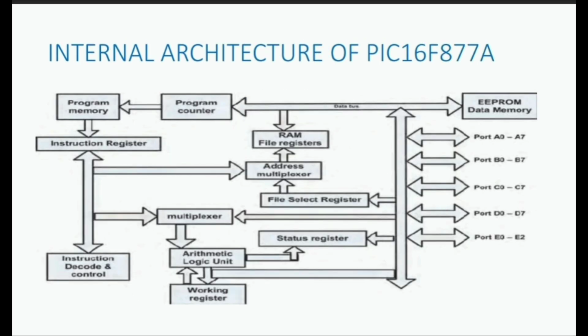So this is the block diagram of the internal architecture of the PIC16F877A PIC microcontroller. The PIC microcontroller is built around Harvard architecture. There are two memories, one for program and the other for data, and they are separated. We can see the program memory and data memory separated by buses.